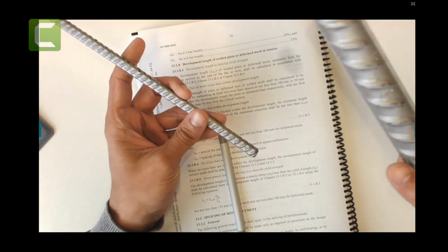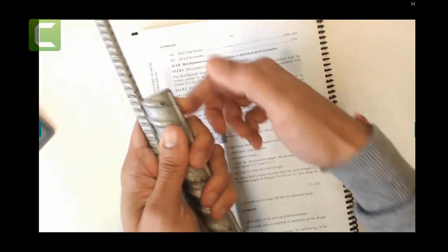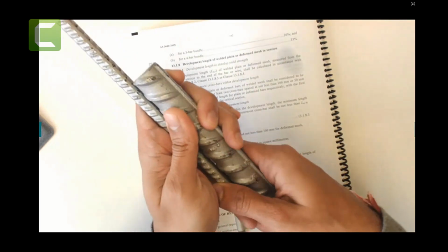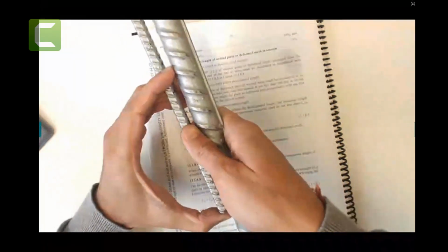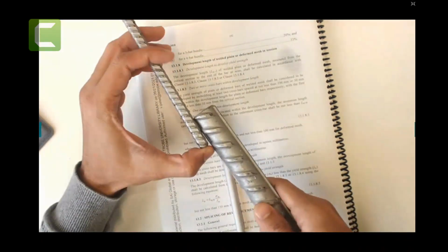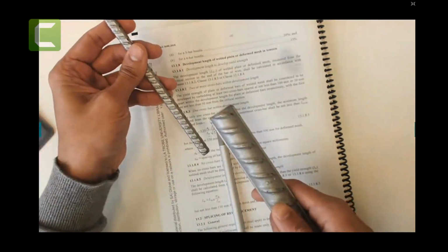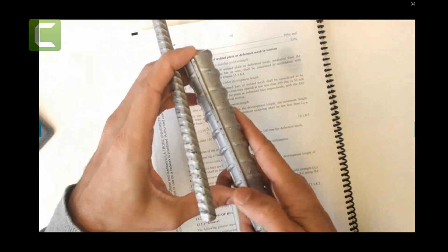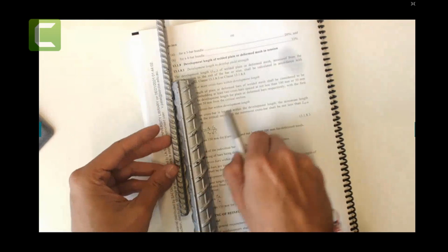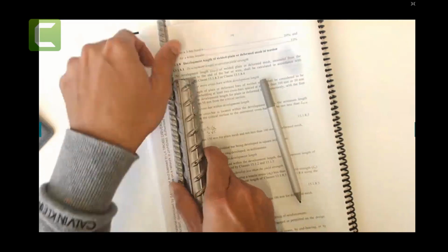Let's say there is not enough length, then you just put another bar on here. You can use wire to tighten this one, and another wire to tighten that one. So how much length should you lap, either small or big? How much length are you going to lap? When it is subject to tensile force, the same force will transfer from this bar to that bar. So I hope you understand. So that is the lap length from this point to this point.